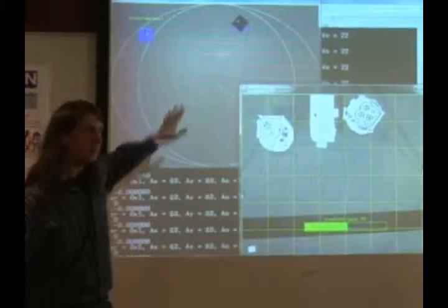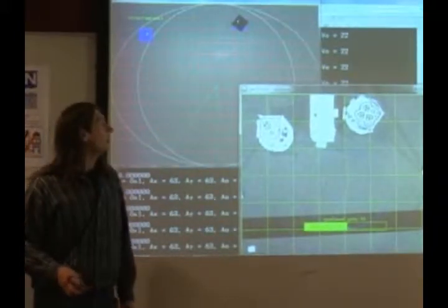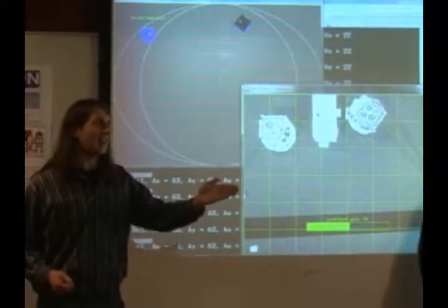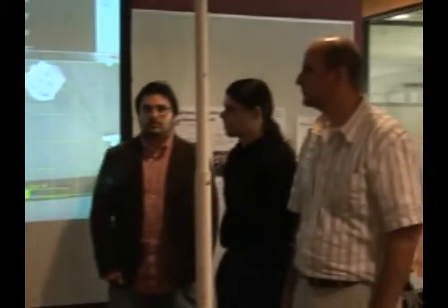As it moves around, it will be sent new packets with updated information to figure out where it and the attacker are. And that leads into our next problem, which was getting the information to the robots, which Ned has dealt with pretty much the entire semester. Right. So we developed a packet-based protocol. We have a header byte as part of the packet that contains metadata about the size of the packet and what type of packet it is. Then there's a payload that contains the coordinates and the orientation, or the angle, of the symbols that it's viewing. And to get it to the robot, we use Bluetooth.